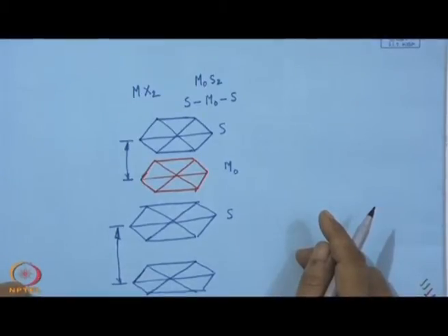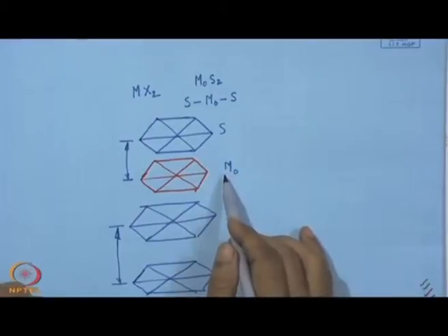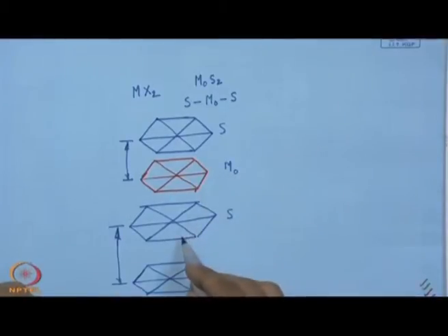So, when a force acts on this plane, the sulphur-molybdenum bond does not break, but the bond between these two sulphur planes, being weak, does. So, this plane can easily slide over the other one, and that ultimately results in a very low value of friction, and it is exactly what we know as the super lubricious property of materials like molybdenum disulphide or tungsten disulphide.